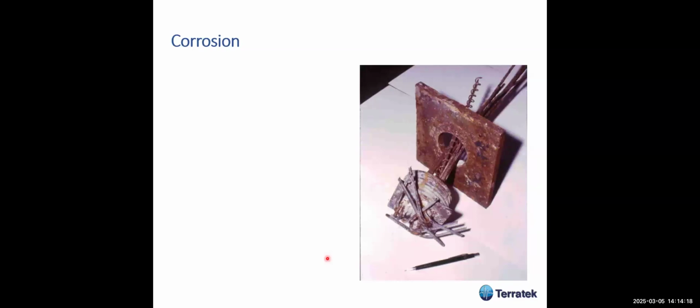I remember a friend of mine once gave a lecture on this kind of bad practice of not protecting these multi-strand anchors from corrosion. And as a matter of fact, I've seen a few failures due to this bad application of multi-strand anchors without a proper corrosion protection.